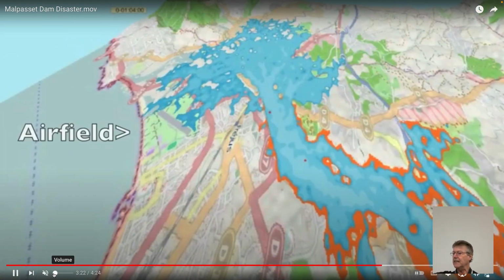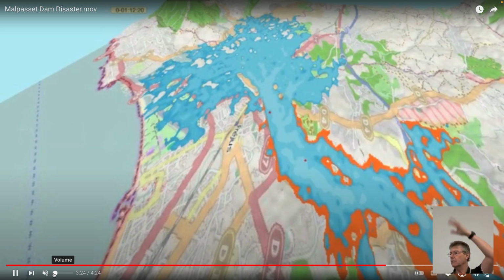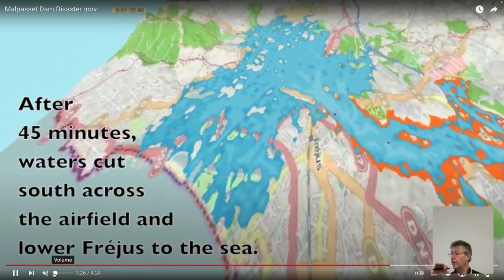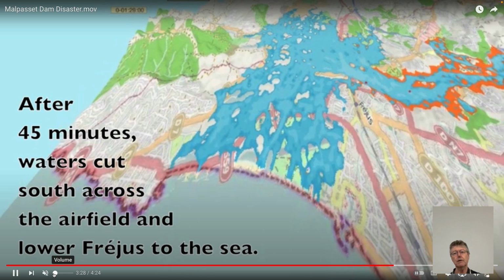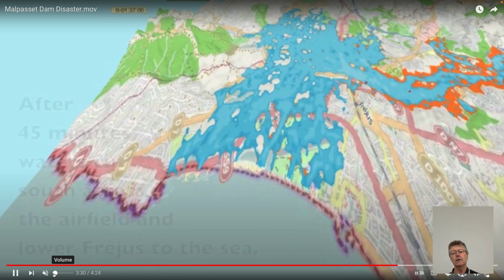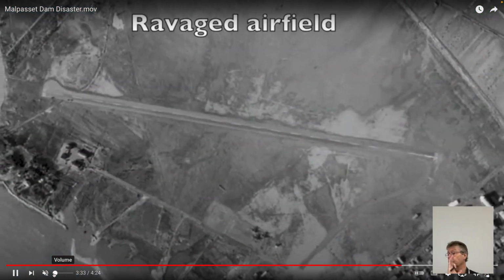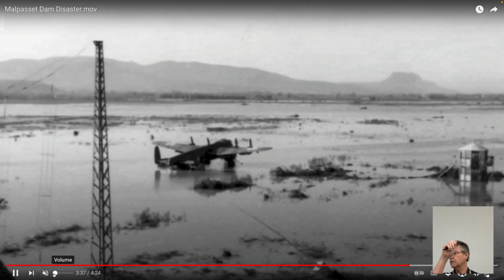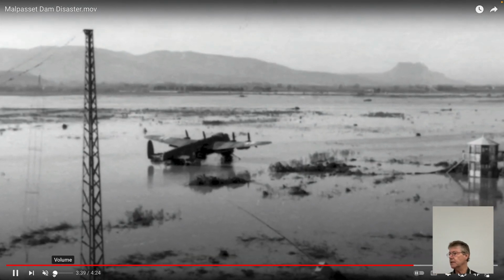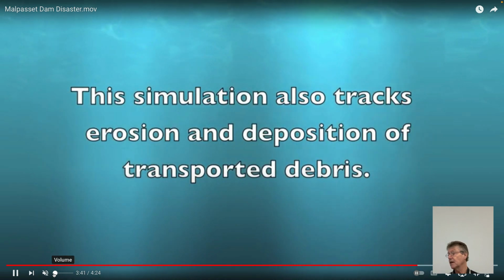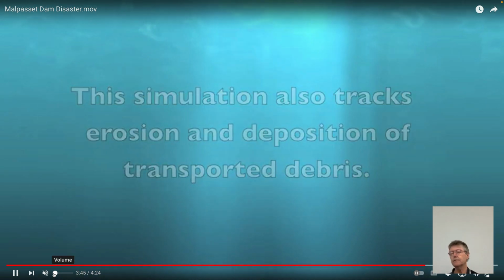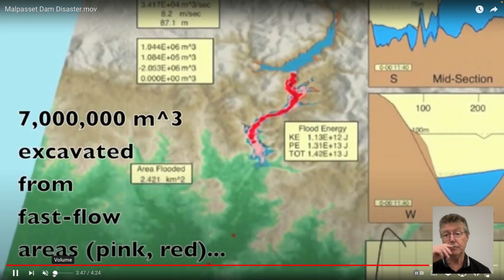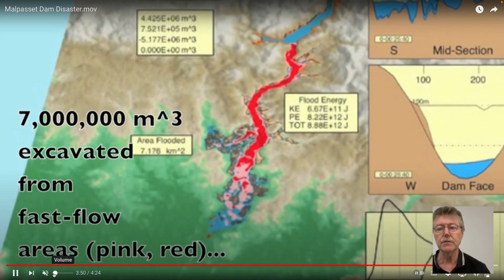If we work in gauge pressures, zero pressure now, we don't need to worry about the atmosphere, but we worry about the water above us when we're down at the bottom of the swimming pool. And so you can imagine that on the wall of the swimming pool, as a result of that pressure, there's a small pressure at the top, and it gets progressively larger and larger as you get to the base. So if you have an above ground pool, you have to design to be able to take care of those forces.